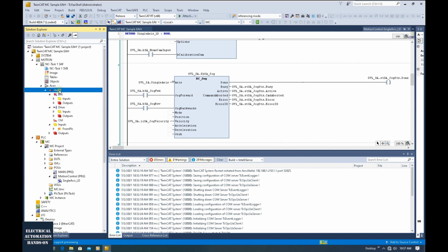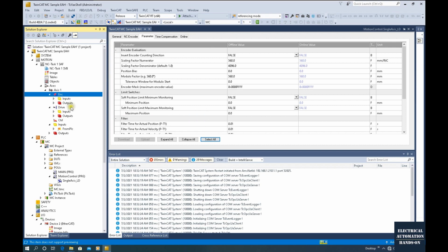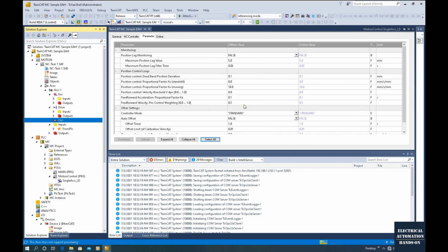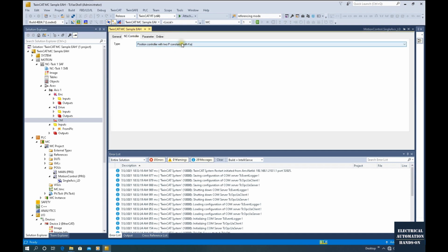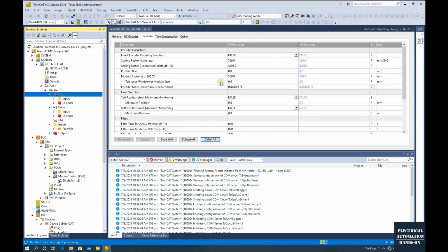One is how we set up the axis, and how we did the parameter setting for the encoder, the drive, as well as the control parameter. In this axis, I'm using the 2K closed loop controller, and for the standstill K, I'm using 8. For the moving, I'm using 10. For the incremental encoder, I set 1 revolution as 360. I assume the degree equals millimeter.